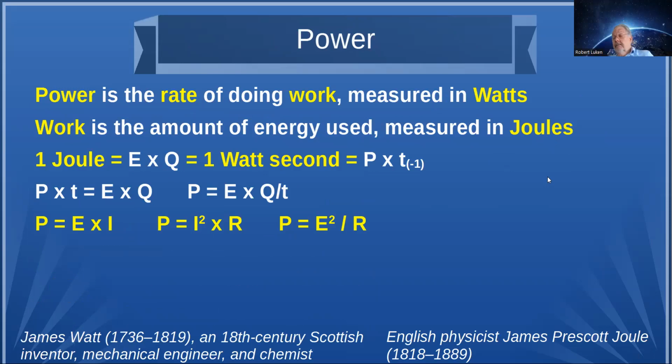Are you talking about antennas? Well, I was talking about the little connector between the transmitter and the antenna, and it said you need a 50 ohm connector between your transmitter and the antenna. Most amateur radio equipment, I'd say 98%, is built to have a 50 ohm source impedance. So they need to be connected to a 50 ohm load.